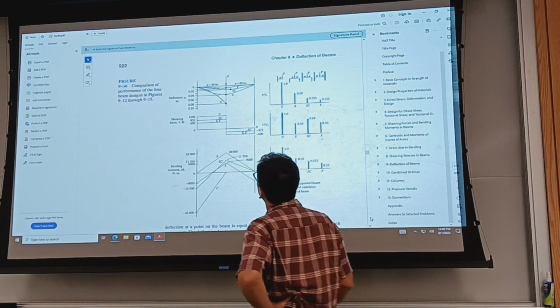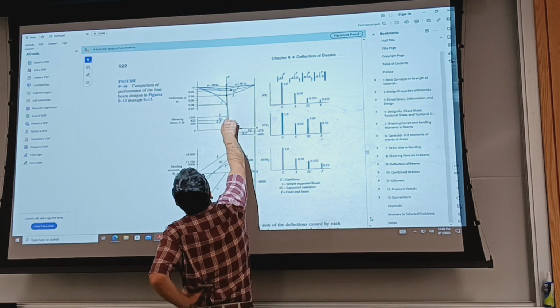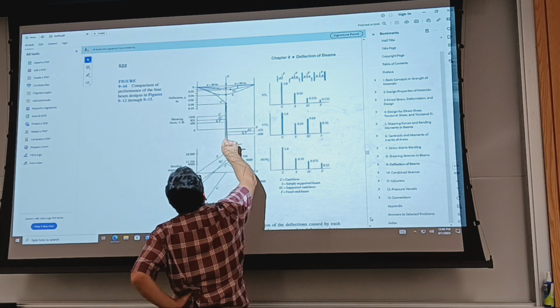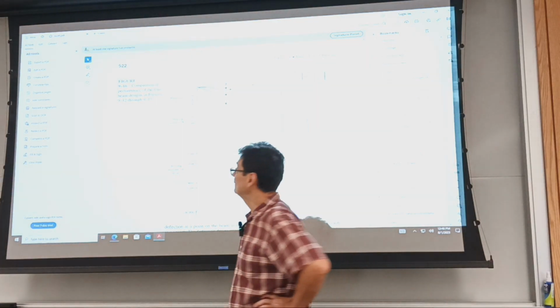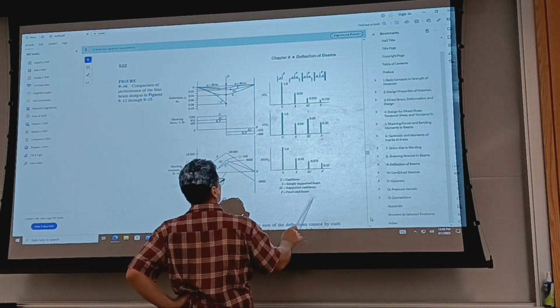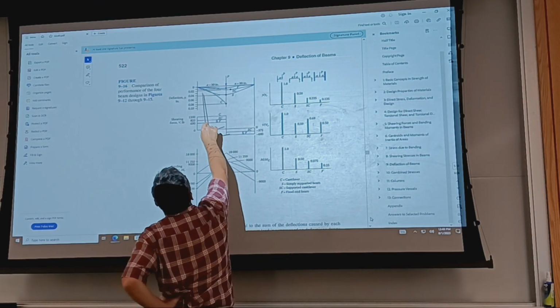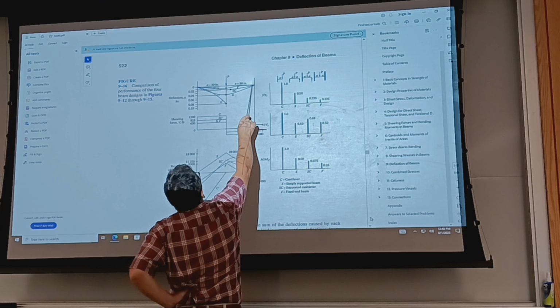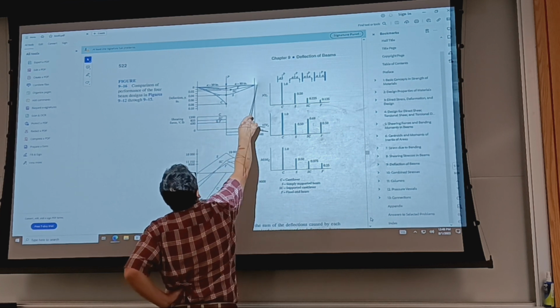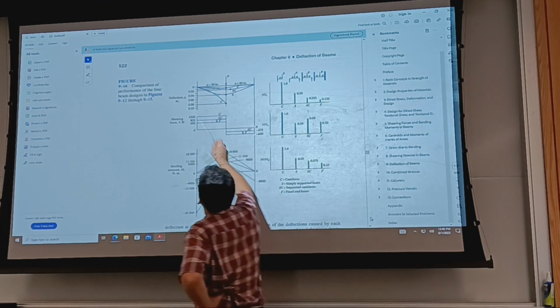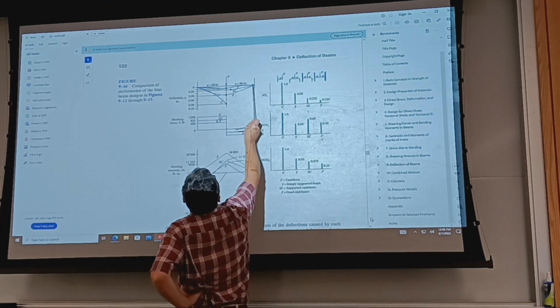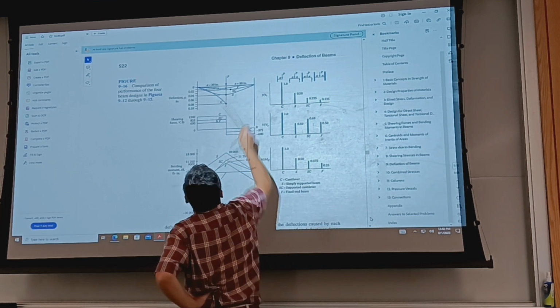And as you can see, for the cantilever, it takes just 1/2 length. In any case, maximum deflection occurs for the cantilever, and minimum deflection occurs for the fixed end beam. Why is that? Because you limit rotation, so the slope is limited to 0 at the support. On the supported cantilever, slope is 0 here, but it is allowed to change.